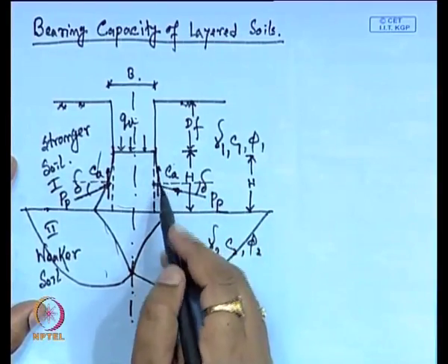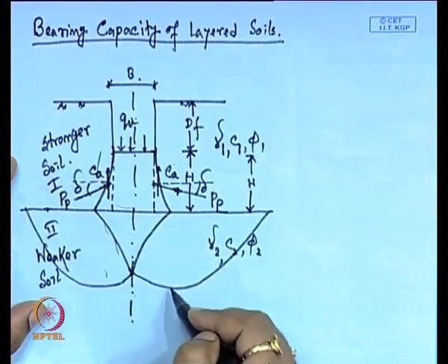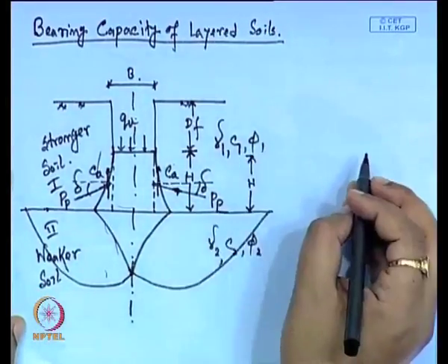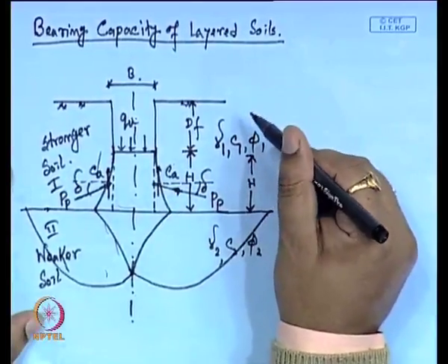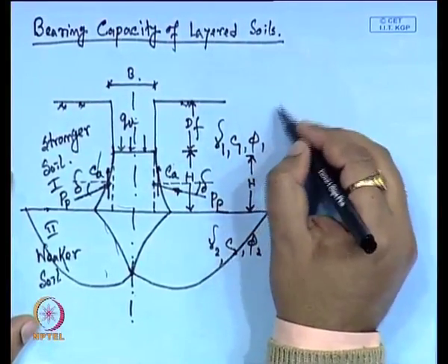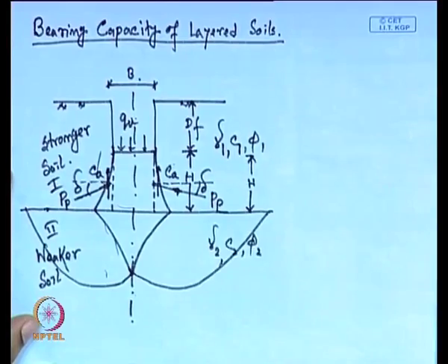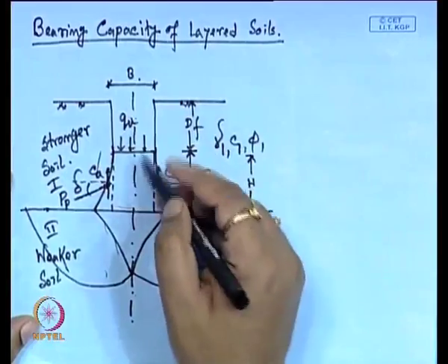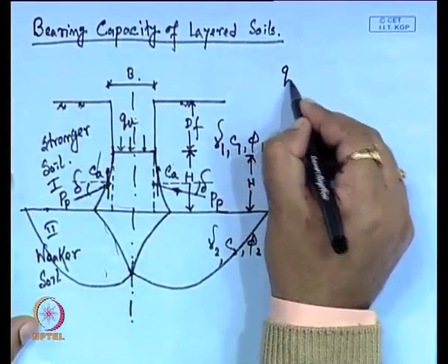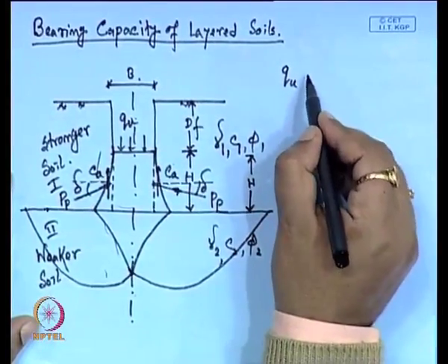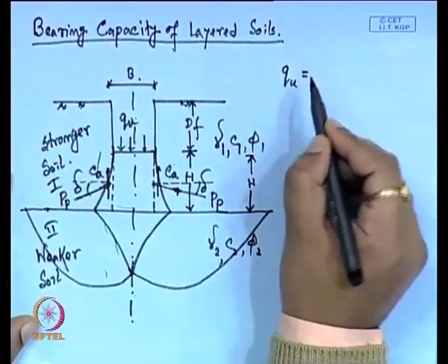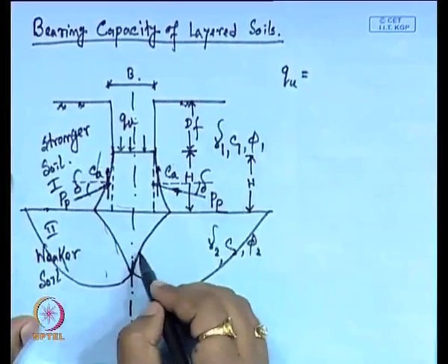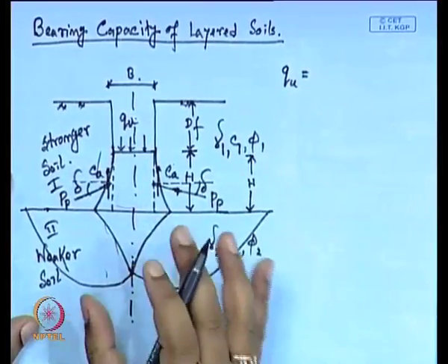Now, if it is relatively small, then we will go for this approach. Now, one thing is that this value. So, if I go for the different loading condition, what will be the different loading condition for this case? First we will calculate the Q u for the vertical load, which is acting in the downward direction, that is equal to the perpendicular load that is acting. So, that Q u is the total load bearing capacity.